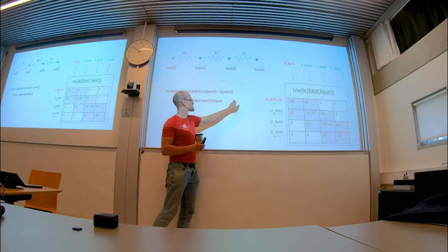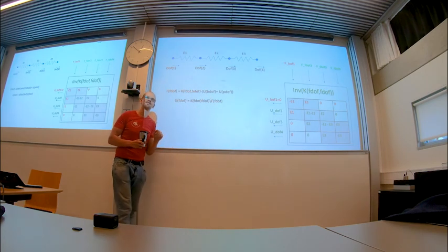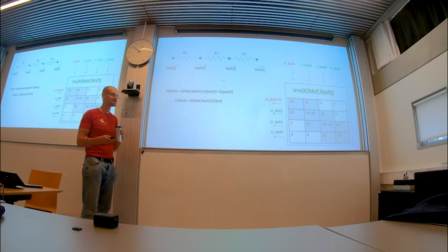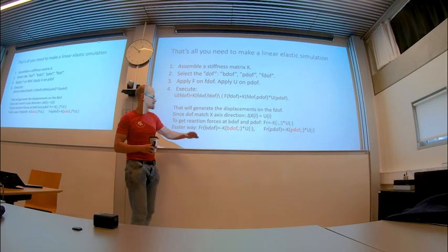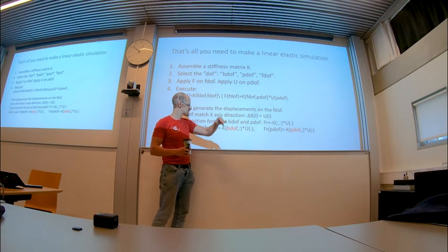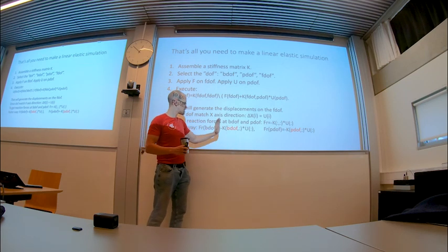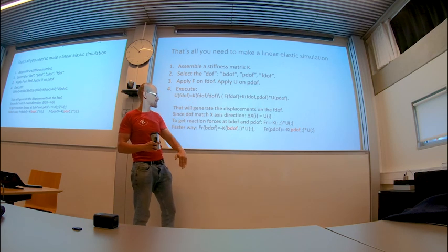Plasticity adds a second plus here, where you have these invisible plastic increments being converted into external forces. And yeah, so you know how to assemble the stiffness matrix. And this again was a graphical thing: this means all the columns are selected, and that means only the boundary DOF lines are selected. Everything else is filtered out.